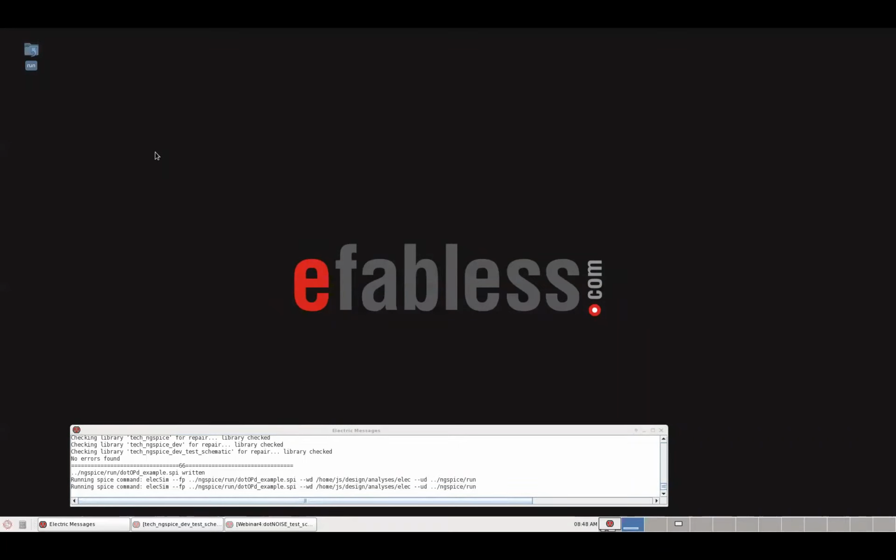So in a way, it does matter. I'm not sure how the explicit power and ground pins affect the hierarchy structure of ngSpice. I haven't tested it so far, but so far we played around with bidirectional pins being readable into a hierarchy element, so if you have two levels of hierarchy, that's the way we should go.